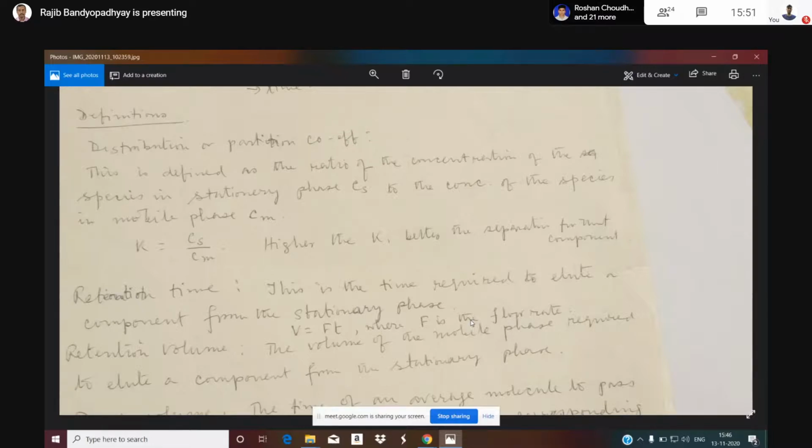Apart from the flame ionization detector, there is another type that I'll also discuss, the thermal conductivity detector, which detects based on the thermal conductivity of the particular gas. There are different advantages and disadvantages, but FID is very popular. Although it is risky in the sense that it needs hydrogen and oxygen, and there is flame generation.